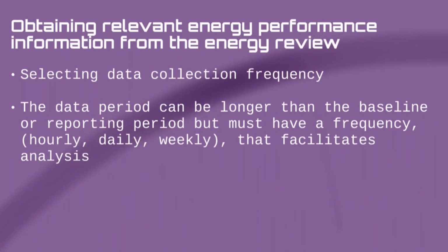Also on measurement, we need to think about selecting data collection frequency. The data period can be longer than the baseline or reporting period, but must have a frequency, an interval, and this is the important thing, so hourly, daily or weekly, that facilitates analysis. Frequency must be right to capture changes in operating conditions.